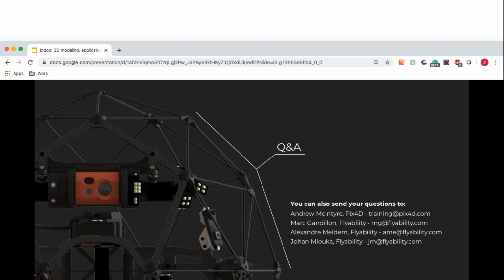The ultimate way to really determine it would be for you to run an empirical test in your own circumstances with your own camera, with either check points or, probably more often in the indoor environment, check dimensions, where you measure a handful of identifiable features using a tool that you have used successfully in the past and that you trust based on your own experience. Then you measure those same dimensions in your 3D reconstruction and you compare the results.